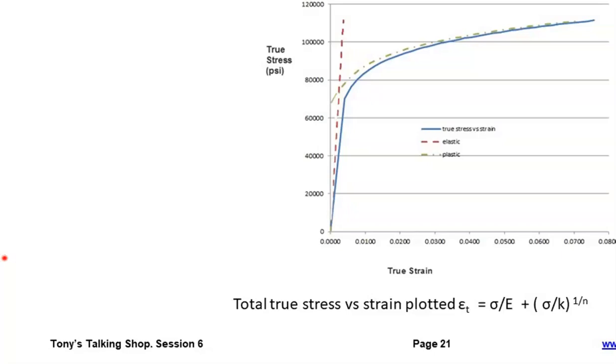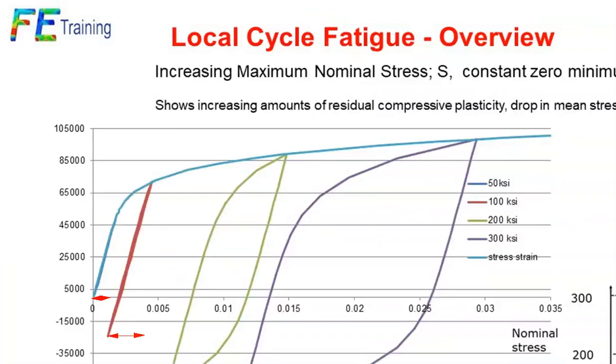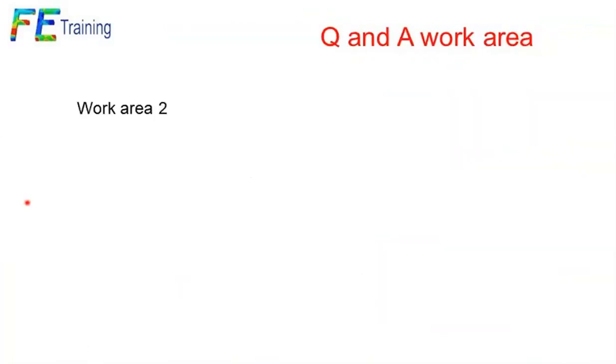What is the effect of R ratio on the fatigue life? This is from Mr. Ali. R is basically giving us the ratio between the fully reversed. So R is -1 means we have, if I can draw, let me go to my sketch area. From bitter experience, it's better to have a clean sheet to start to draw these things. So what we've got is that fully reversed means that we have a fatigue history which is going from plus and minus load the same.